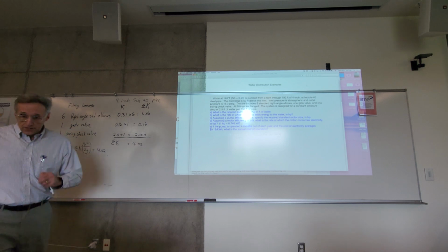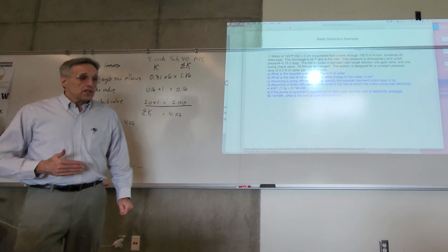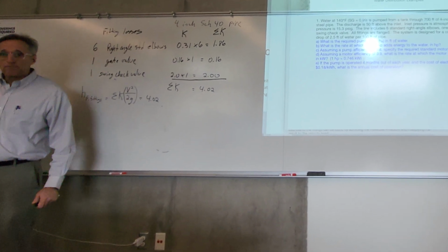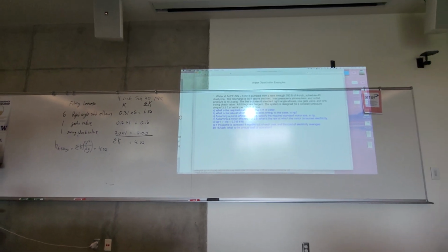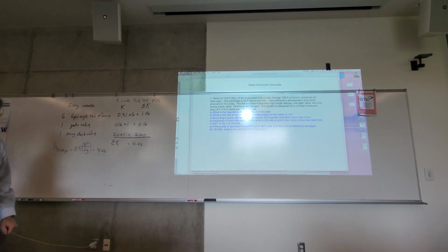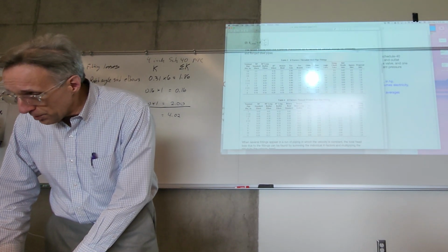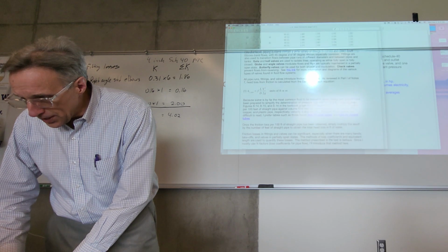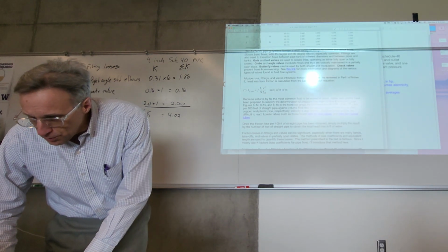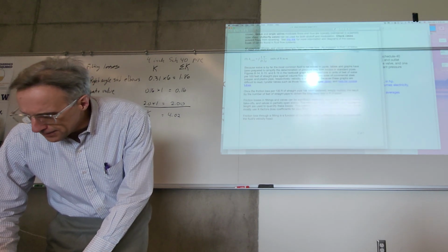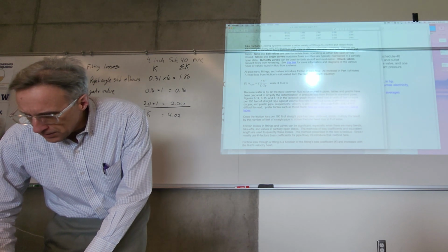Yes, but the easy way to do this is we either can use the graphs in the chapter for head loss for various sizes of copper and steel pipe, or my preferred approach is to use tables for the particular pipe that we're using. This is a steel pipe, so if you go into the notes here on page 2, there's a link to tables.